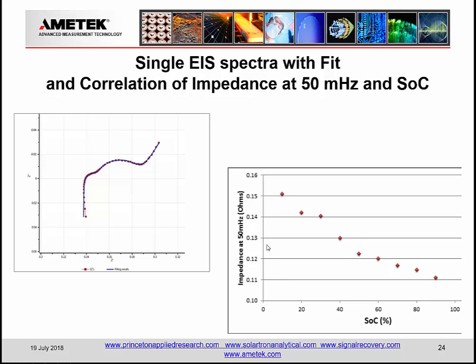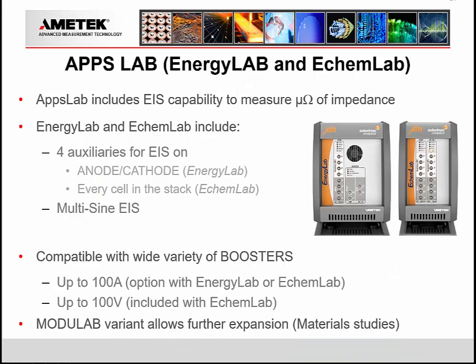And then you will know going forward that if you have 0.13 impedance level, you can roll over here and scroll down on our calibration curve and find out we've got 40% state of charge.